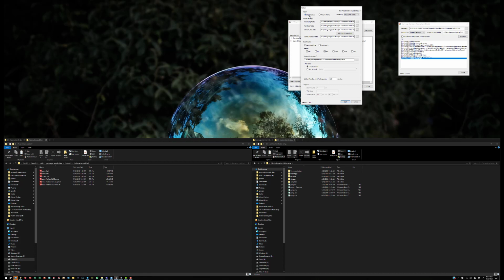So I go single source if you have a single file that you need to inspect, which is typically what people need to do, is they take a single scan in and inspect it to the CAD model. What you do is point now to those folders. So you point to the monitoring folder, which is what I would call the watch folder, and I'll explain that here in a second. You point to the template folder, which is going to have the Control X inspection file that we created earlier.